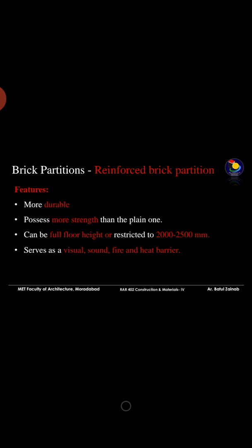So, the features of reinforced brick partition are they are more durable, they possess more strength than the plain one, which we previously studied, can be full floor height or restricted to 2000 to 2500 mm, serves as visual, sound, fire and heat barrier.